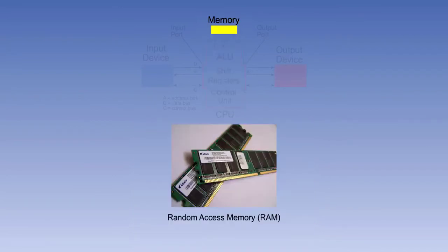If a program has to be changed during operation, then the memory must be able to be written to as well as read. To do this, random access memory, or RAM, needs to be used as well as read-only memory. With this type of memory, data can be written in, read out, and altered at will. RAM is also required to store the data for processing, as this also will change continually. Memory that loses data in the event of a power failure or switch off is called volatile memory. RAM is normally volatile memory, so any data stored in it is lost in the event that the power is removed.